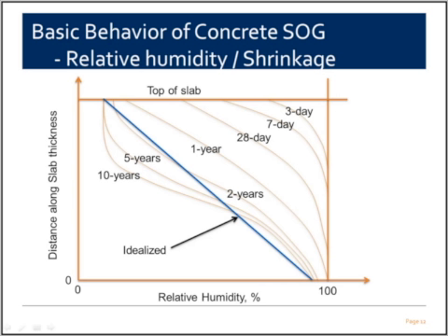And I have drawn here the possible moisture distributions, relative humidity distributions with age of slab, at 3 days, 7 days, and so on up until 10 years. I've just drawn these things. You might expect to see it on a slab cast directly on ground or not protected for moisture from underneath.